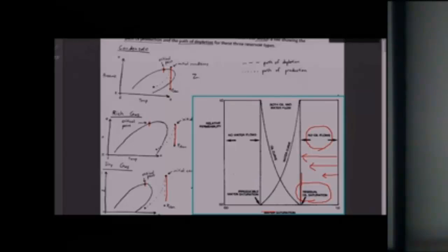will it hit a dew point? Because if it doesn't hit a dew point, I can design all that recoverable gas, some recovery factor times the gas in place, to process the liquid. So I may design my plant one way. But if I have a dew point reservoir, I may only have a short life, maybe 6 months, 8 months where I produce that much liquid, and then it's going to produce a lot less liquid. And if I build a plant to handle that much liquid over a long life, I'm going to waste a lot